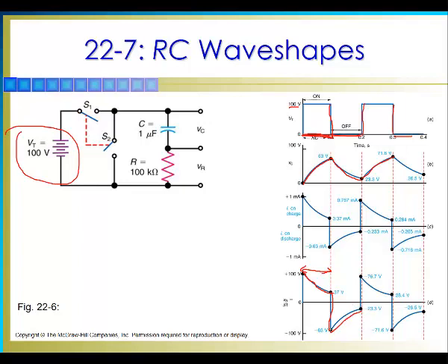This is when the voltage source is disconnected, the capacitor is now discharged through the resistor from the other direction. That's why it's negative. Now the voltage on the capacitor starts discharging on the resistor, and that's why it goes up like this. And then the voltage source comes back on. That's 100 volts. So from here, 100 volts will bring it up to this point, and now the capacitor starts charging. So the voltage on the resistor starts decaying. You just have to continue doing this.